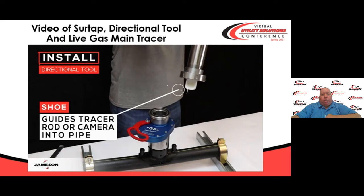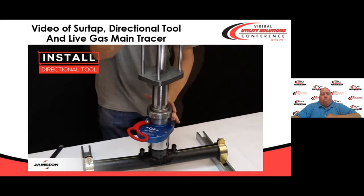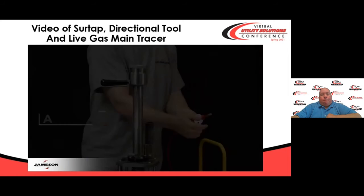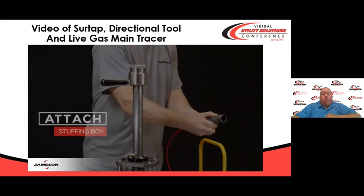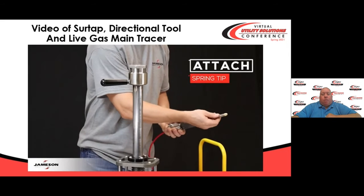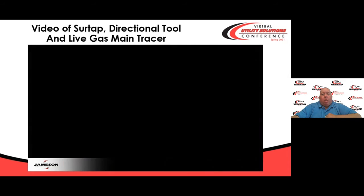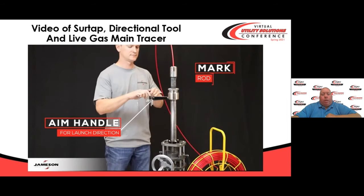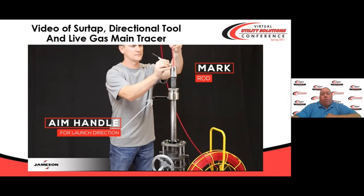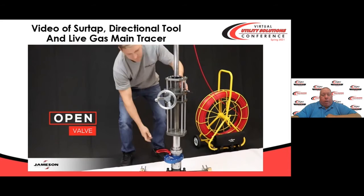Now they're going to install the directional entry tool. Notice the cup there that's going to guide the tracer rod or the camera into the pipe. This shows attaching a stuffing box to the top of the tool so that they can insert the mainline tracer. It's got a spring tip that helps it navigate through the pipeline. Once that's assembled, they're going to connect it to the Jameson directional entry tool. That handle there is going to indicate your travel direction.